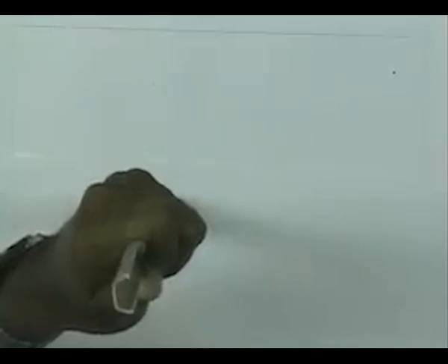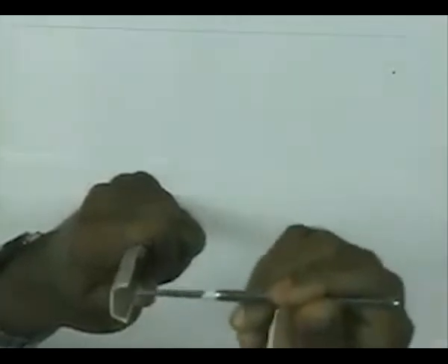You will find this type of problem more often coming up for sections which have one axis of symmetry or no axis of symmetry. In the case of I section, you have both the axes of symmetry, so you do not have this problem. But in a C section like this or L section, you have only one axis of symmetry, and you will have this problem if the loading is parallel to the axis which is not an axis of symmetry. So, let us see that if I now try to put a bending load like this,